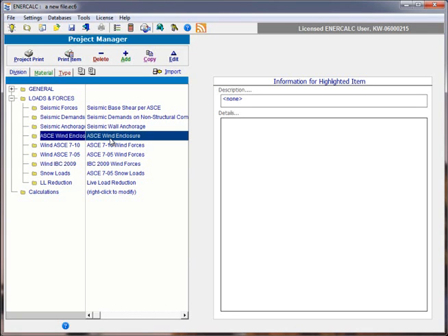And so what we did was we created this worksheet that simply collects areas of openings and areas of gross wall expanses, so that you as the user can populate those values and work your way through a logical thought process to let the computer make the determination as to whether a building qualifies as either enclosed, partially enclosed, for wind on a given elevation of a building, or potentially if a building actually qualifies as an open structure.